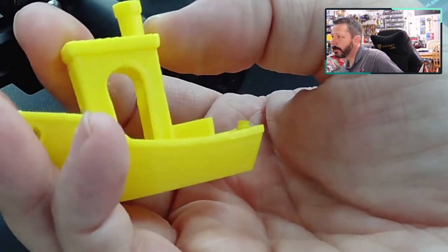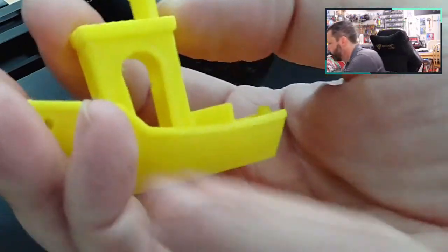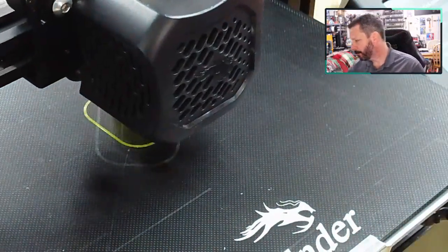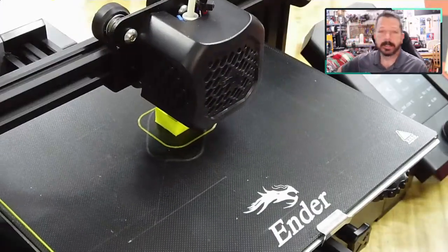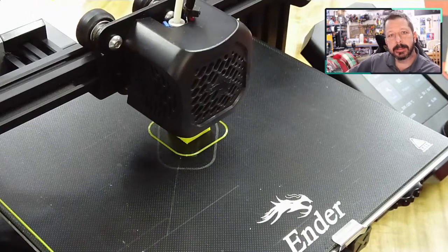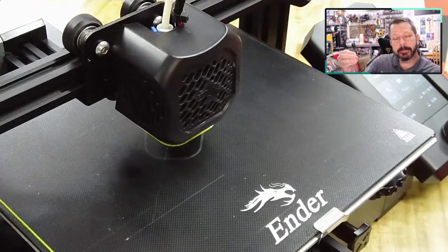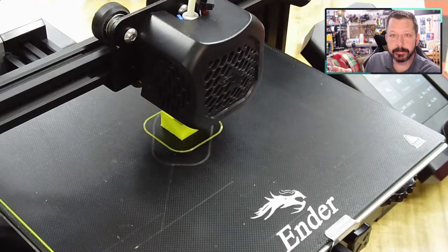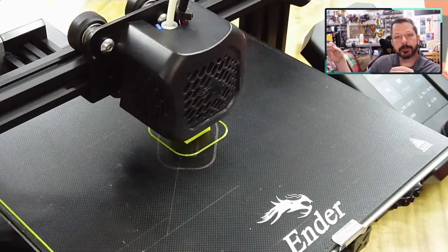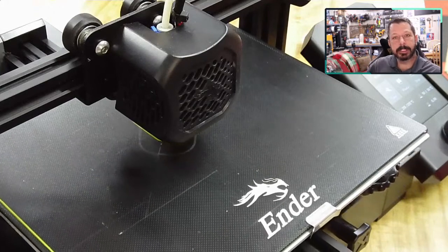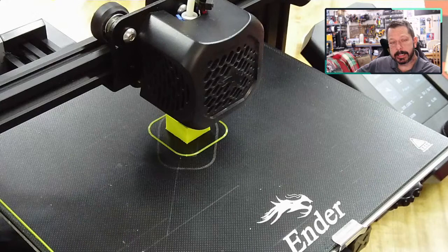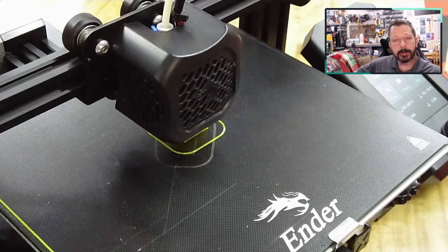Those are from the nozzle wanting to print over here, move into an empty space, and print again, and while it's moving in that empty space, get a close-up of our print. While it's moving into that empty space, the filament that is in the nozzle is sort of liquefied. It's very gooey, and it will string across those empty spaces. And so you can reduce those stringing things in a couple of ways.